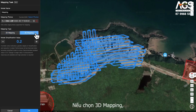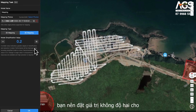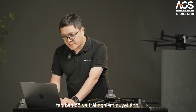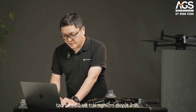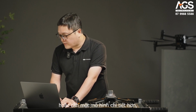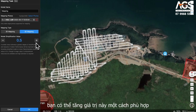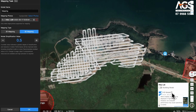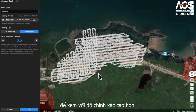If you choose 3D mapping, it is recommended to set a value of 0.2 for model simplification to improve the mapping efficiency and browsing experience. If you have a high-spec computer or require a more detailed model, you can increase this value appropriately and enable HD model to view with higher precision.